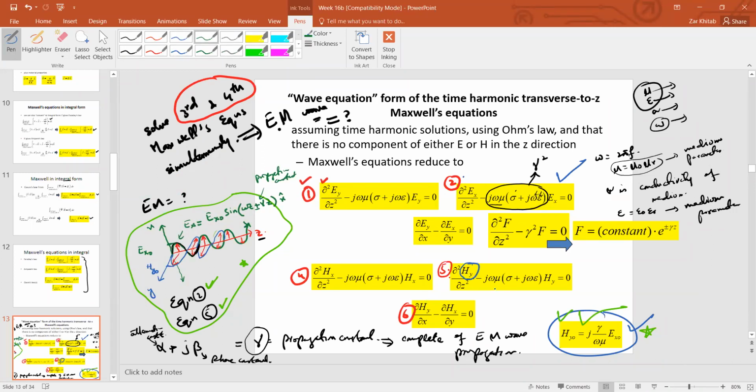Okay, gamma is the propagation constant, which is shown here. This is gamma. This is gamma square. Okay, this thing is gamma square, right? So gamma plus minus omega t, omega is the frequency. So I can really make this thing. If I know this equation, I can really calculate the magnetic field. Magnetic field will be Hy, sorry, Hy. This magnetic field will be Hy equals to Hy naught sine of